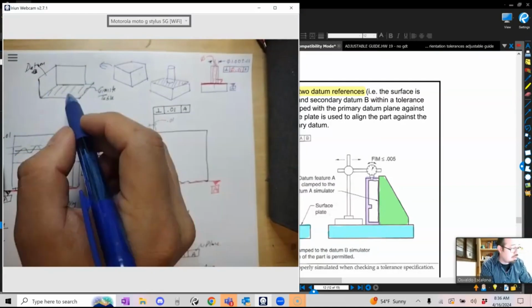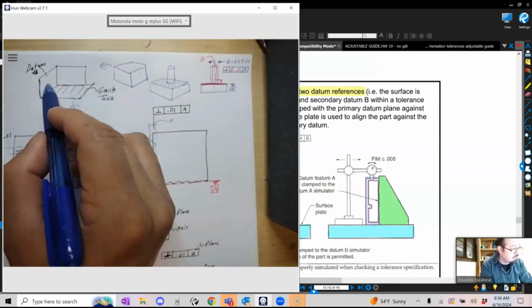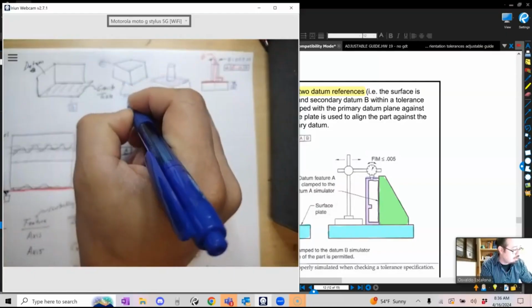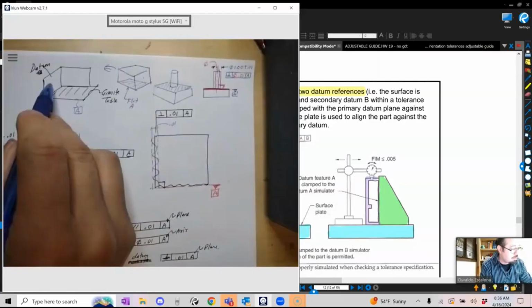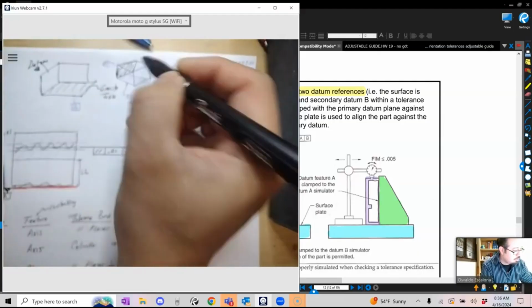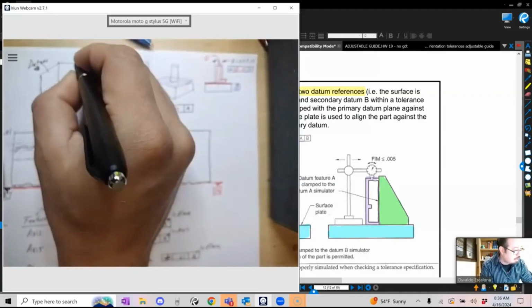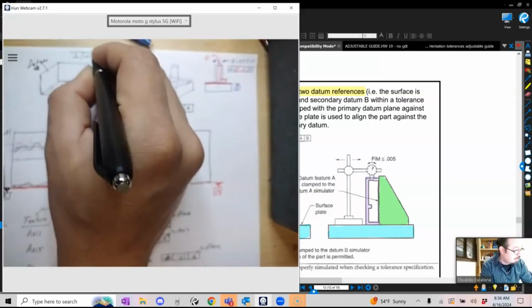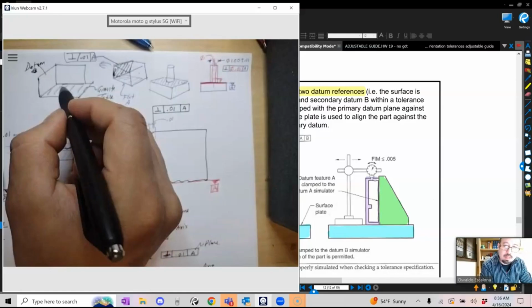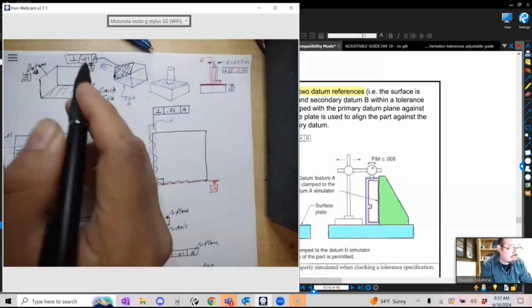And then right after that, maybe I can control the perpendicularity. So let's say it's a flat datum A, and maybe I can control perpendicularity on the left side. So perpendicularity on the left side, control it. After I do it, I'm going to call it perpendicular 15.1 to datum A. So you will put this part, we'll bump it against, and then I'm going to call it datum B, after I establish it.